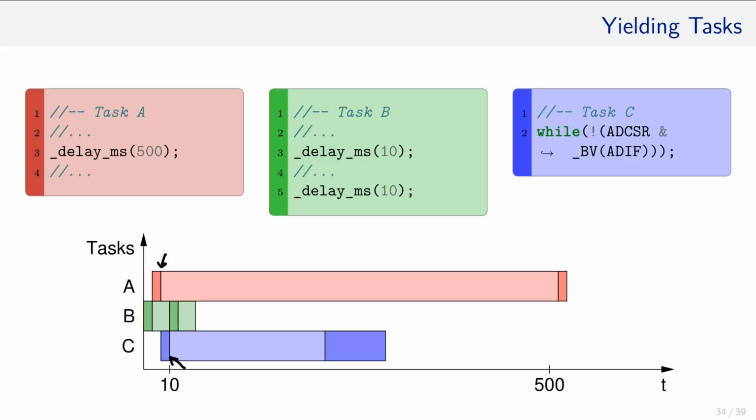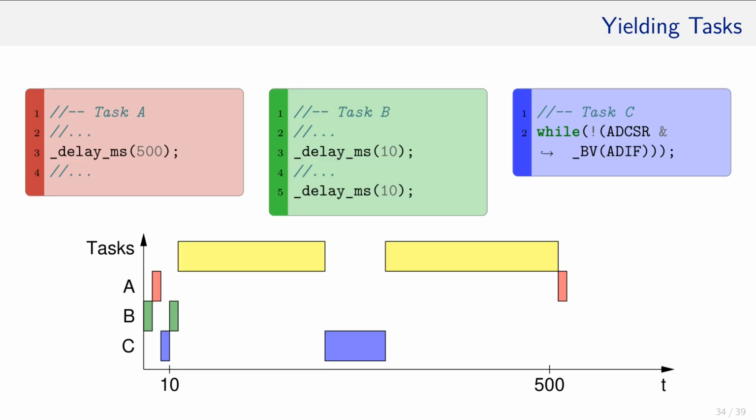The scheduler could register those requests and make them part of its decision logic. And even better, the scheduler knows what task is waiting for what and can let the MCU sleep to reduce the power consumption. That would be ideal, wouldn't it?